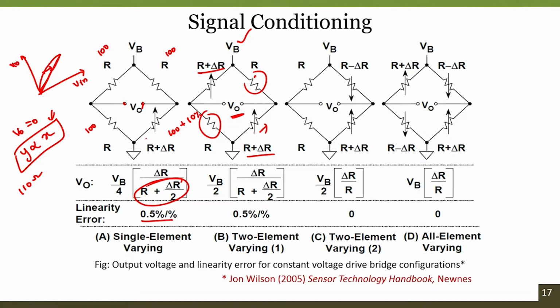When we have the same resistance change, the effect will never be seen. So, that is the reason for temperature compensation: if the sensor we are using is only for temperature compensation, adding a resistor at this point is always an advantage, provided that the sensor should not change with respect to the input load, input parameter or input measurement, it should only compensate for the temperature effect.